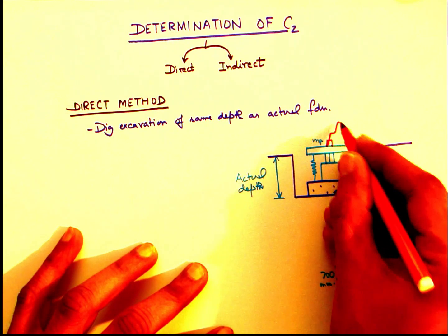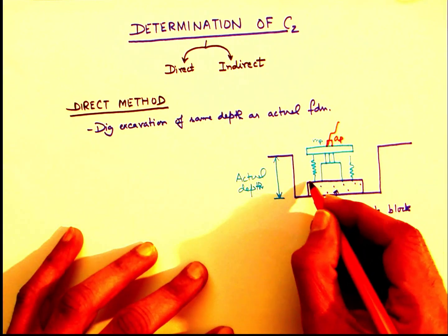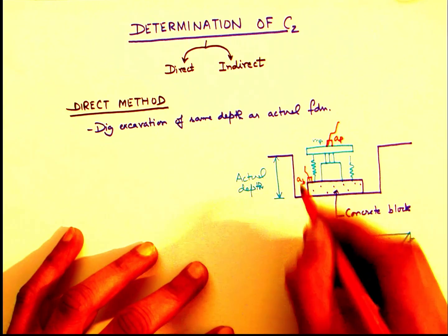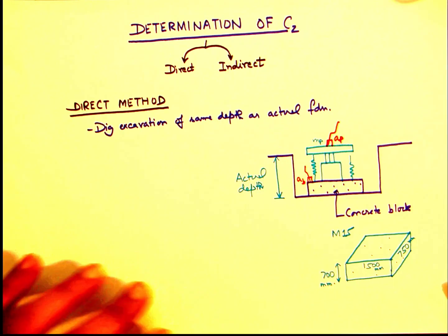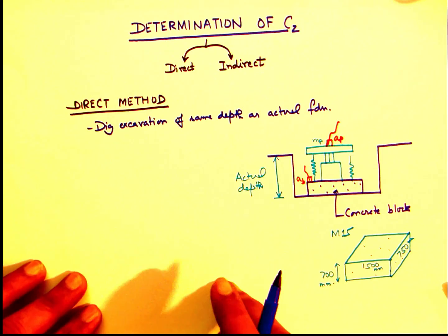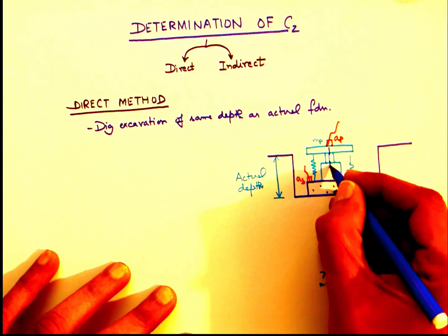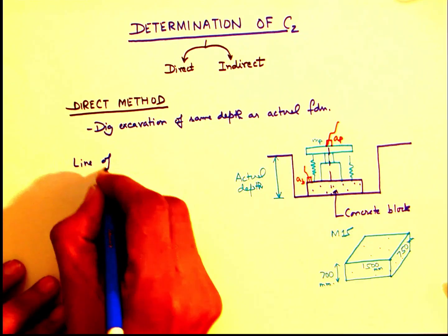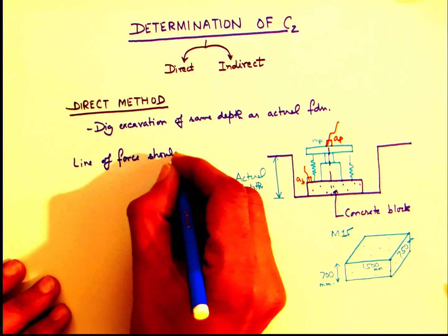So here we are describing the measurement using the electrodynamic shaker type equipment. For that purpose we need to measure the acceleration at the top of the top plate and also at the base block. So let AP be the acceleration of the top plate as shown here and AB at the base block. So we need two accelerometers to be installed as shown here.